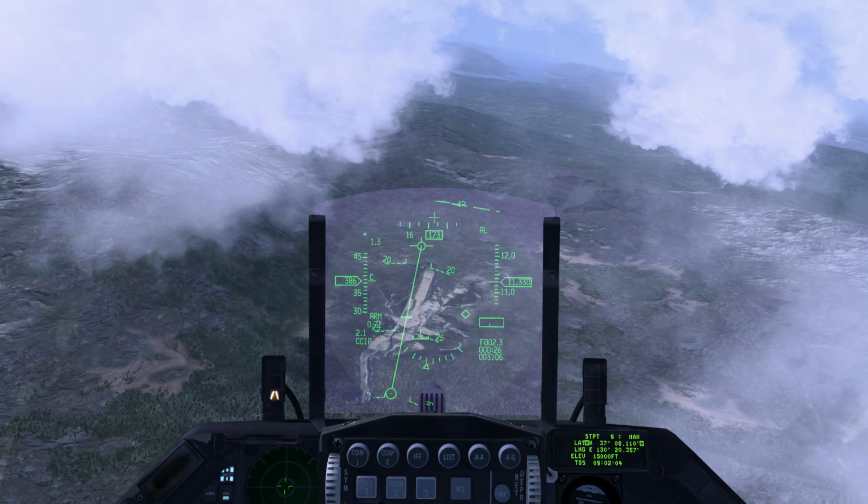We will not place the pipper directly onto the target, rather we will line the aircraft up on the BFL and allow the pipper to walk onto the target as we approach it. 3 to 5 seconds on final is fast enough. Don't rush it any more than that by pulling the pipper up to the target. When the pipper is over our aim point, we will press and hold down the weapon release button or key. The FPM will flash when weapon release has been completed.